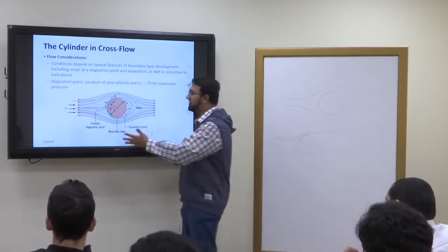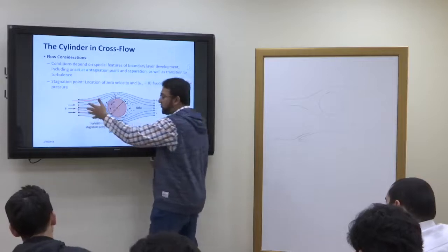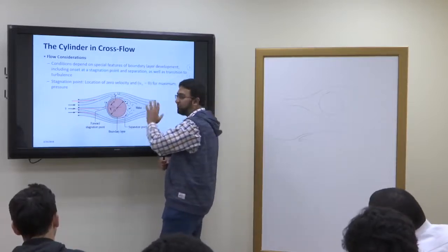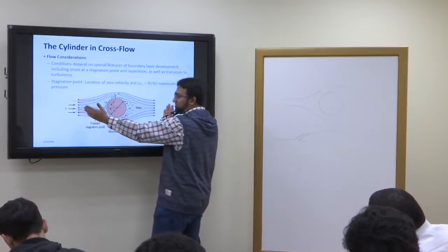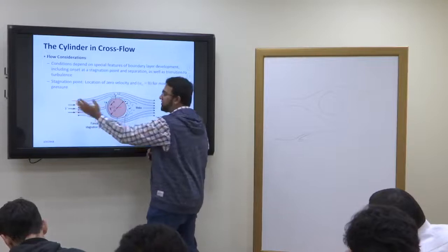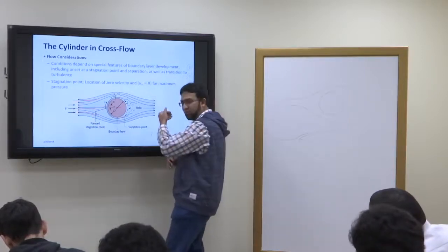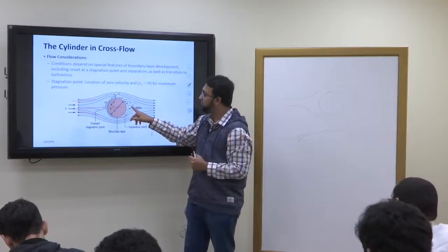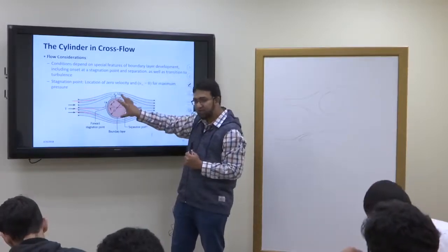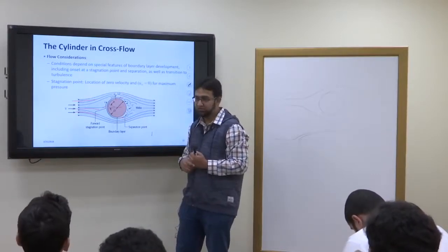The pressure gradient here was negative because as you move across the x direction, the pressure should drop. When there is a pressure difference, the flow will move in this direction: high pressure here, low pressure there, so negative pressure gradient, and the fluid will flow. However, because of the wake region, the negative pressure gradient will become a positive pressure gradient after a certain time when it is passing across the cylinder, okay.